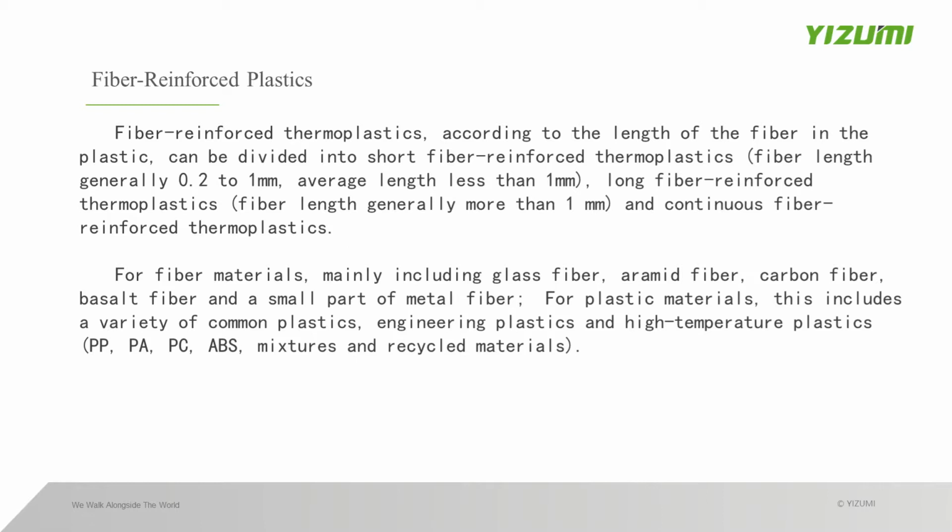And also we have a limit. As before, the limit is 10 millimeters. We should think this is the limit for the long fiber. But now, in the current situation, the pellets we can produce by compounding or pultrusion can be 25 millimeters. And the other type is continuous fiber reinforced thermoplastics.